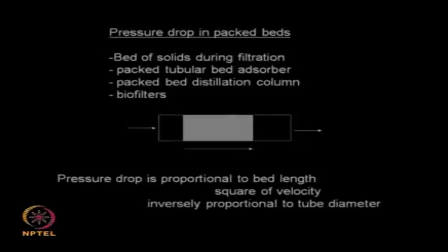Now you also have to consider pressure drops, because when you have a packed bed and a solution flows through it, whether it is a gas or a liquid, the fluid can flow only through the interstices, the packing material offers resistance, and so there is always a pressure developed.